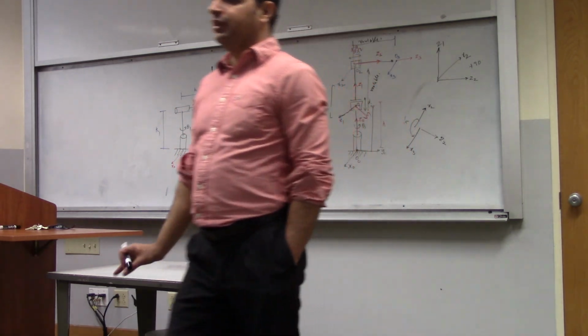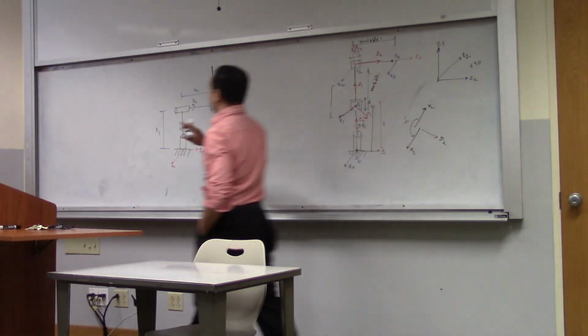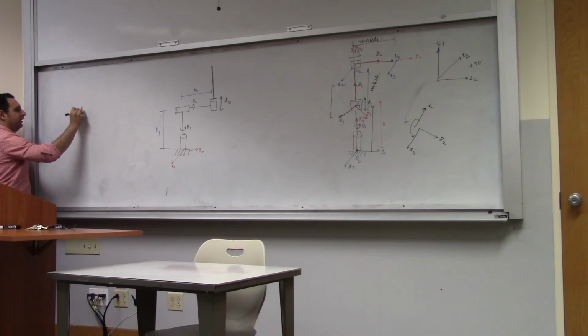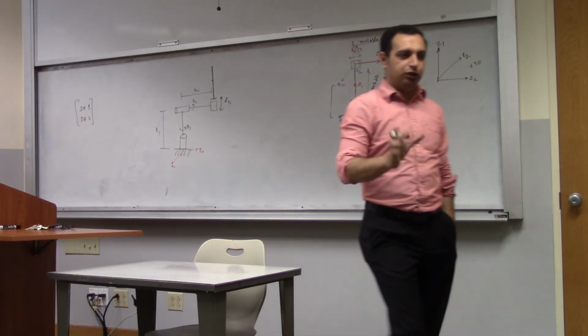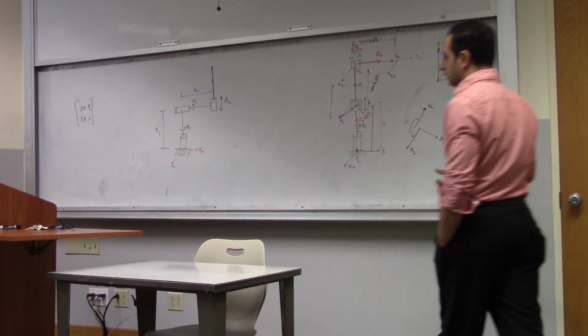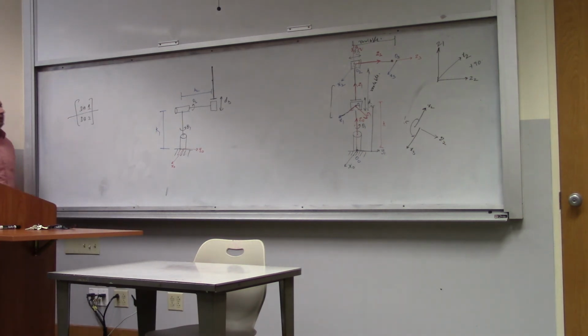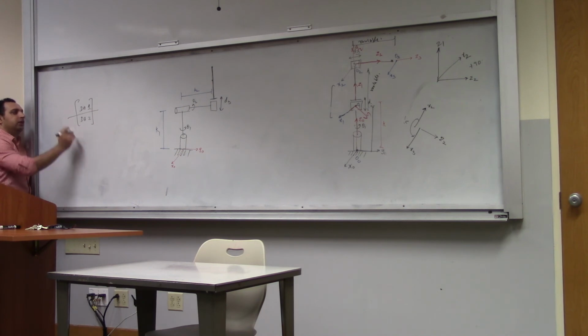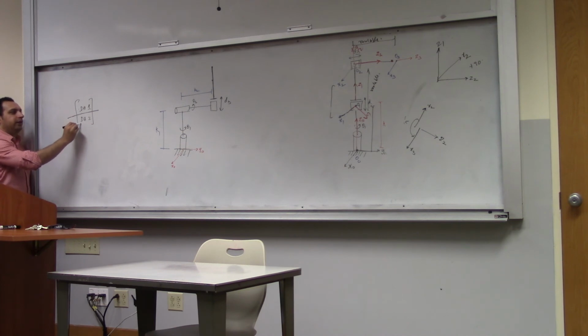Now again, if you come up with a different set of axes, it's not a problem. Always check if you're satisfying these two rows at every selection of x. If these two are not satisfied, it's wrong. So long as these are satisfied and you come up with a different set of axes, it's perfectly fine because you always have a choice of selecting x or the origin. So what I draw is not the only answer. Obviously, you can have a different set of axes, but eventually we should end up with the same transformation. The only way to ensure that is DH1 and DH2.